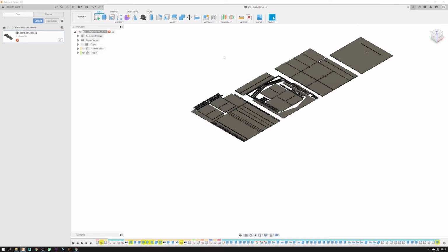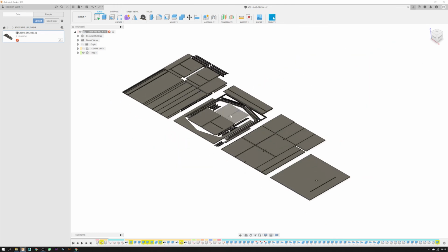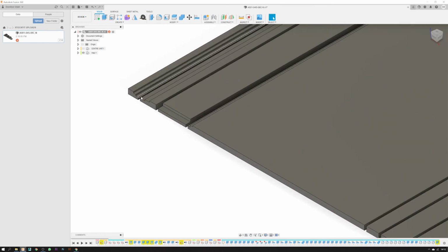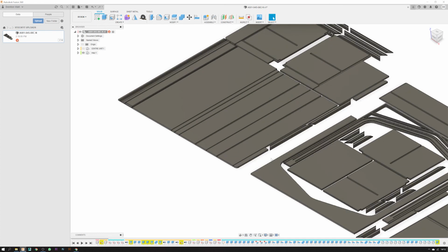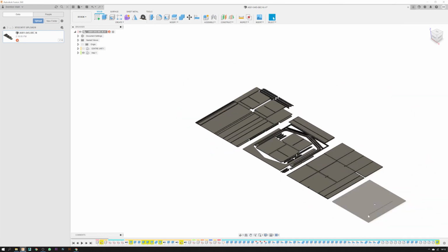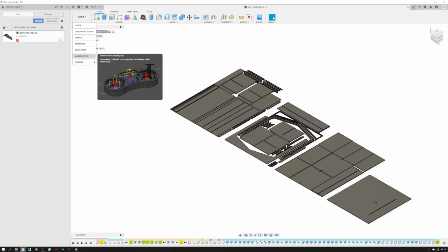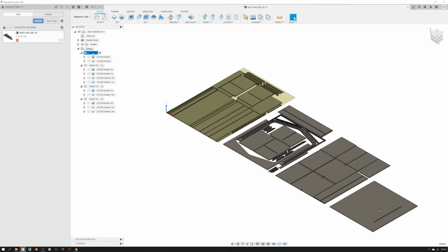But for this exercise, we will simply go into the actual model, flat packed, all these panels that are pretty much ready to go, and you can start machining. If we go into the manufacturing tab over here, you'll notice that the first setup is for all of this. You've got tool 1, which is a pocket cut and a contour cut.